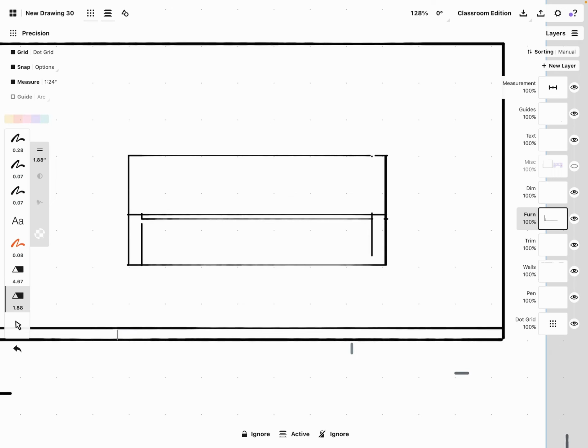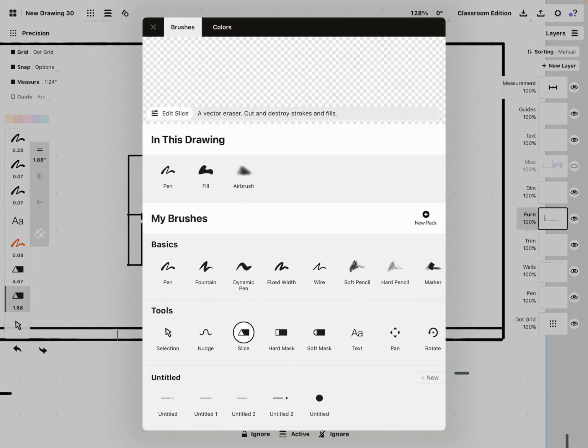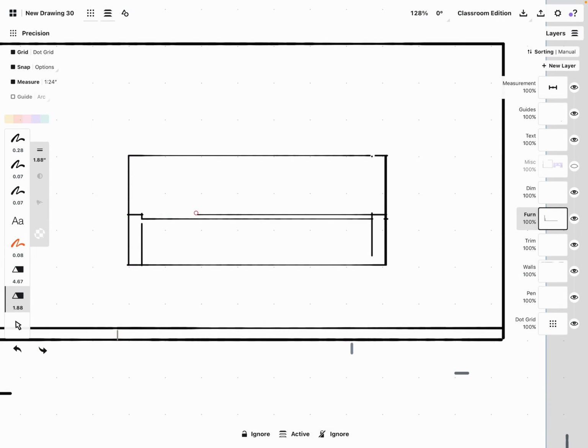If you need to continue lines down, you can. A way to stretch a line down is to select it with your arrow. And where we have scale off, we want to click it so you can go to stretch, and we're just going to stretch it down. And the same here, I can stretch it up.